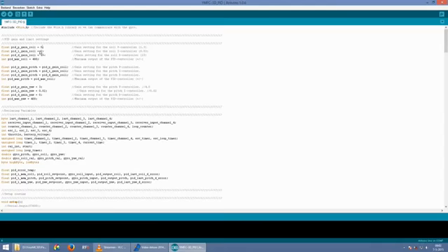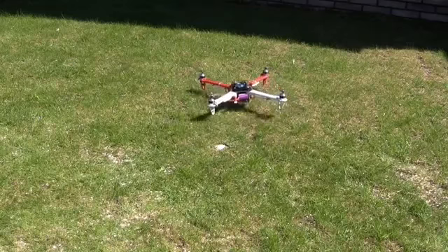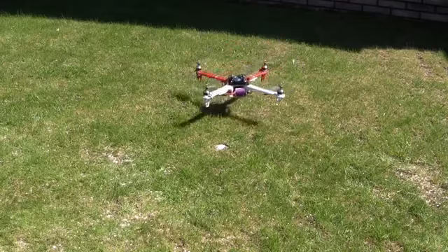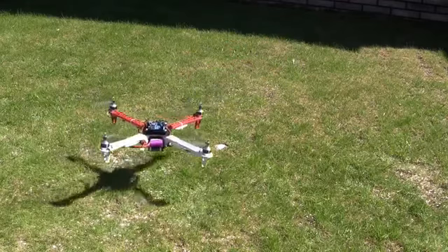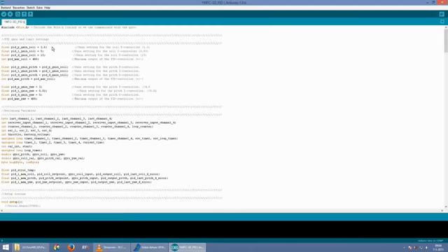Now start increasing the P gain in steps of 0.2. With a decent P gain, you should be able to fly the multicopter. Just keep it nice and low and increase the P gain until it starts to overcompensate. Lower this P gain by 50% and keep this as your basic P gain setting, giving me a final setting of 1.3.